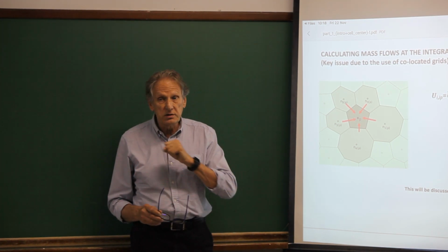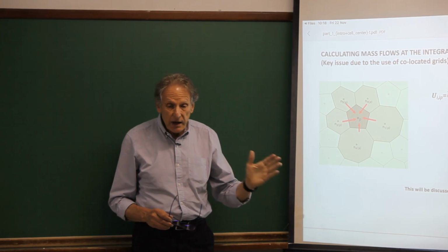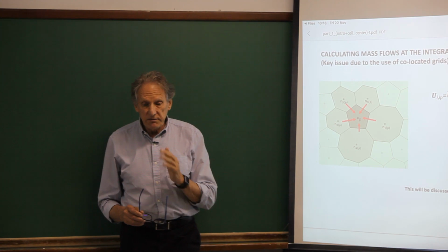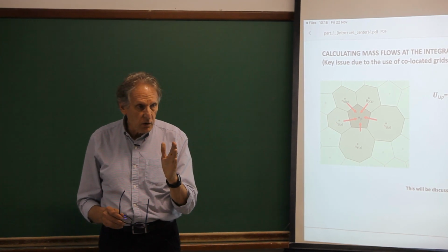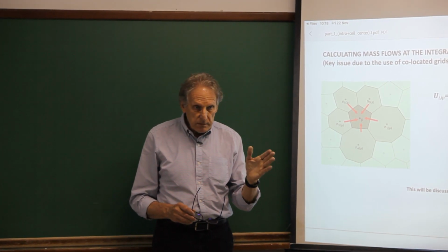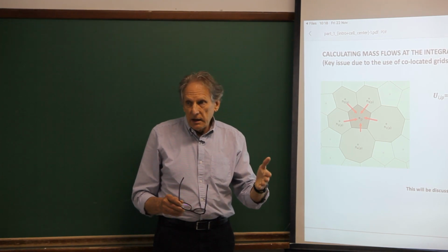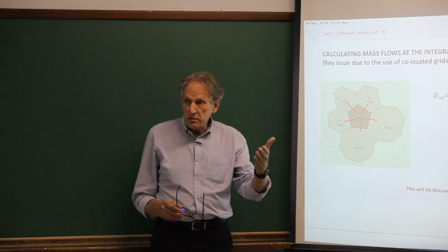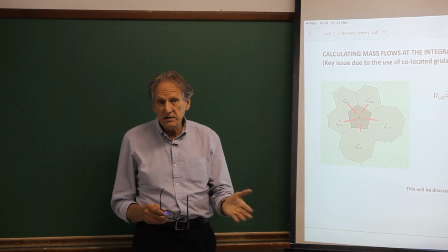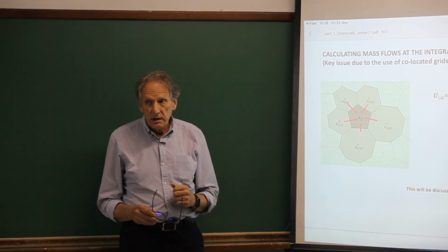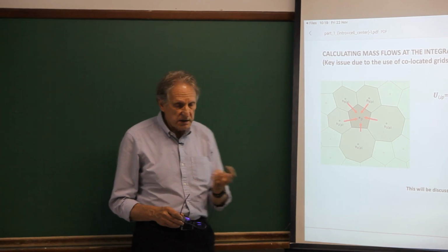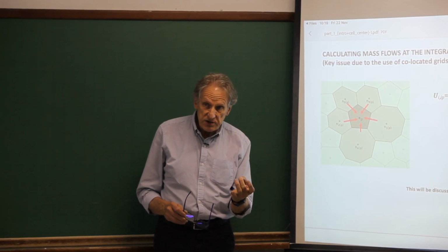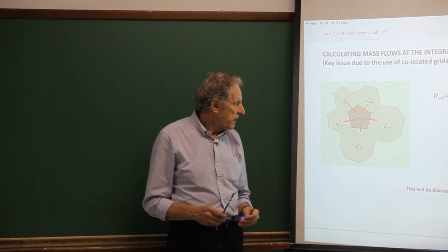And see the importance in having the mass flow very well calculated. I just mentioned mass flow carries all other properties. If you don't have a very good calculation of the mass flow, you are, let's say, introducing errors, and also in the other variables, not just on the mass flow, because mass flow carries all the other scalars. It's like momentum in x, y, and z direction, energy, and so on.